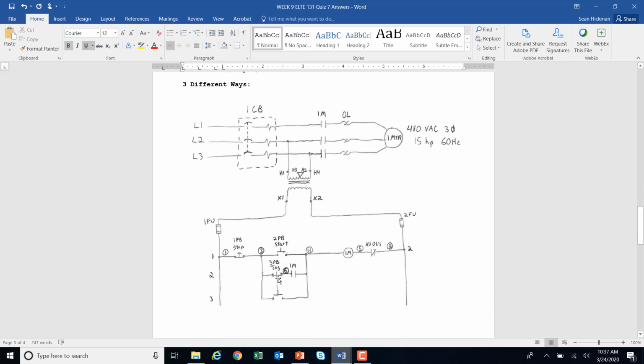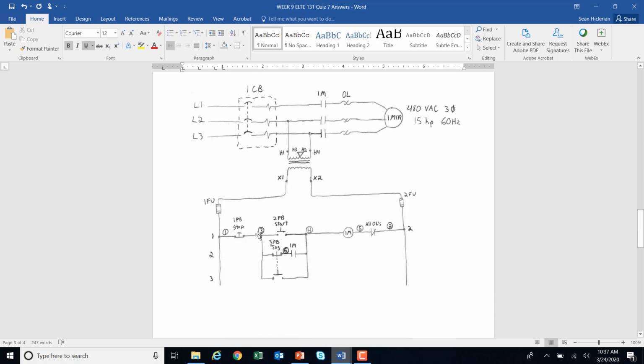So we had the start and we had the jog that would make break. Start just brings this one on, and we would get the motor contact here, and because this was closed, it would work. And let's say we wanted to jog. Well, when I push the jog down, my path would be on the lower rung, and this one would open, so therefore the motor contacts would never come in. That's a make break jog.